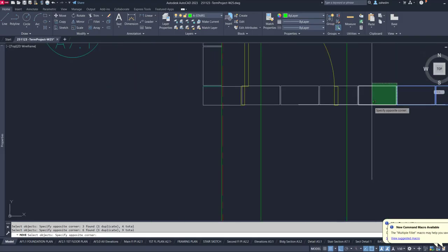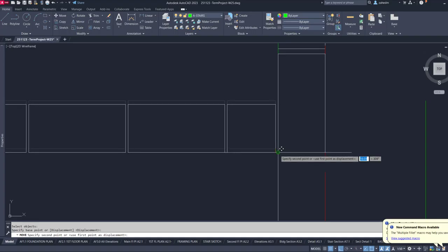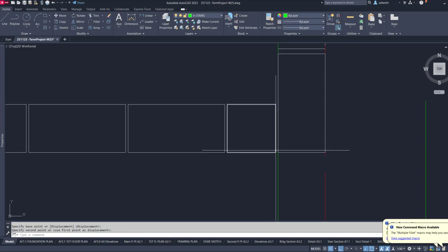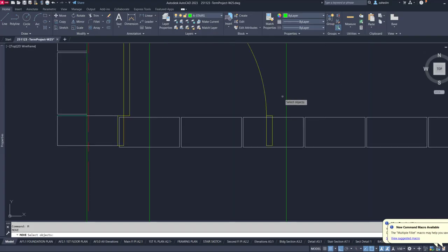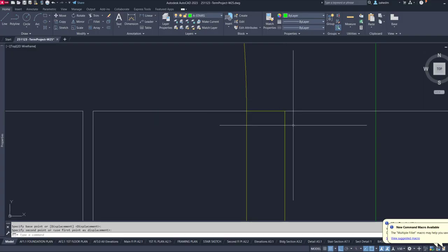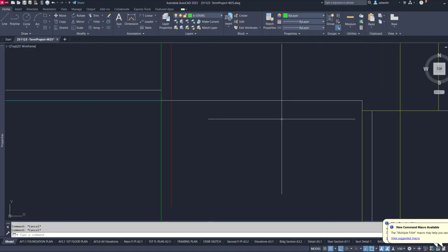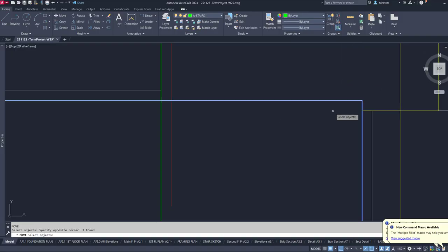I am playing with these graphics to make it constructible, to make it square, and making sure that what I am drawing right here is constructible. If it's not constructible, the working drawing is worthless. So we have to be very careful about what we are doing and measure it as many times as needed to make this drawing as accurate as you can. Otherwise, even a few millimeters here or there is going to be problematic.